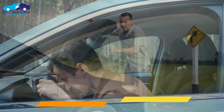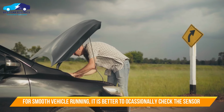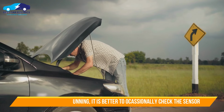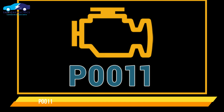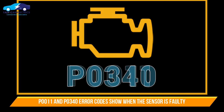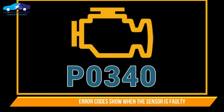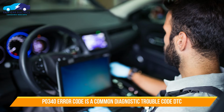To make sure that your vehicle runs smoothly, you must keep checking the camshaft position sensor of the vehicle as soon as it shows the symptoms of going bad or faulty. P0011 and P0340 are some of the codes that are related to the camshaft position sensor of the vehicle and are in effect most of the time when the camshaft position sensor of your vehicle is faulty. The P0340 error code is a common diagnostic trouble code, DTC.